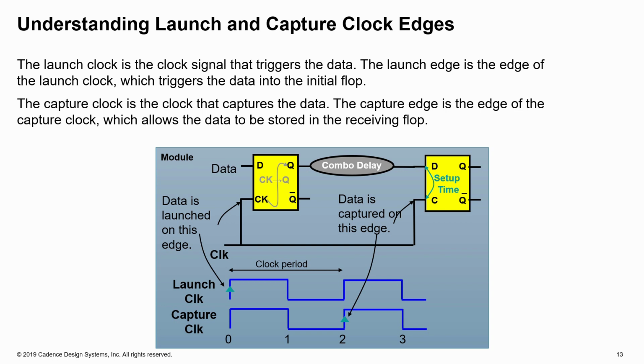And there are certain requirements before a particular data signal is safely stored in the flop. So you need to determine whether that data has arrived at the right time, and if it has satisfied certain requirements, which we will call setup and hold requirements, and we will talk about these later on.